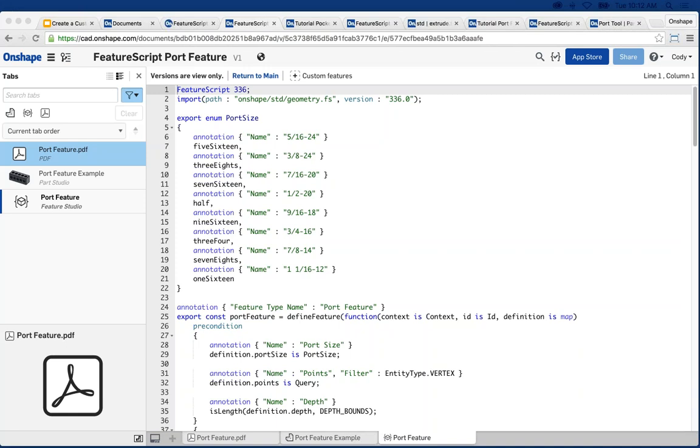So you don't have to have FeatureScript being the source of everything that's being created in the Part Studio. You can have a whole bunch of features that all build off of each other that are a lot more reusable, like building blocks for a regular Part Studio that can encompass a whole bunch of workflows. You can imagine having all the standard features for your company that are all used to create a bunch of similar feeling parts, but which are all ultimately designed by a person using these robust features that you create.